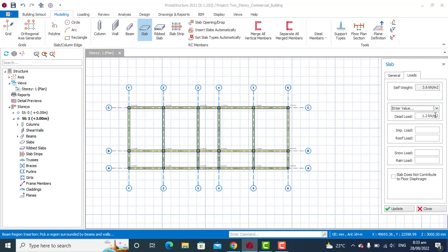So in any event, you also want to check in for the standard room additional dead loads. We have some of the options right here you can select. So if it's a normal room, you can select. If it's a terrace or a balcony, you can also select, and the software will automatically calculate the additional dead load. So I'm going to select the normal room, which in this case is 2.375.